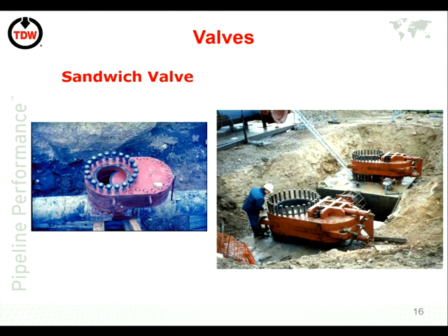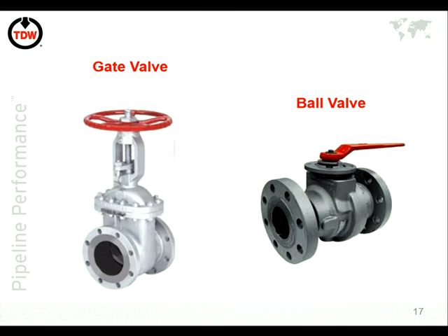There are other valves which can fit on there, obviously a gate valve or a ball valve, and there's no reason that we wouldn't use that as the fitting and the isolation method during the hot tapping. But generally speaking, if that was to be done, it would be done because that valve would remain on there as a permanent feature.